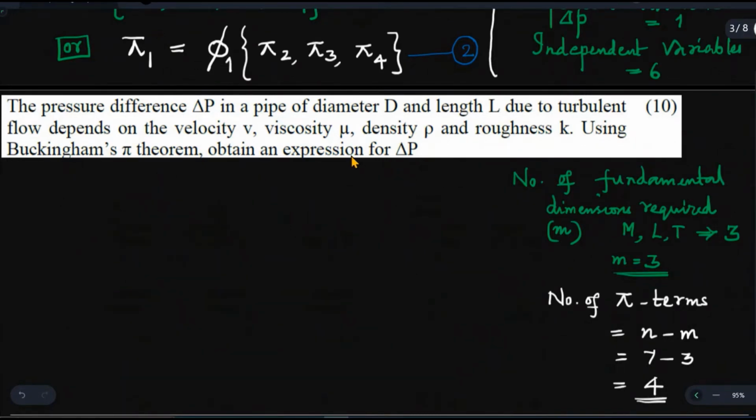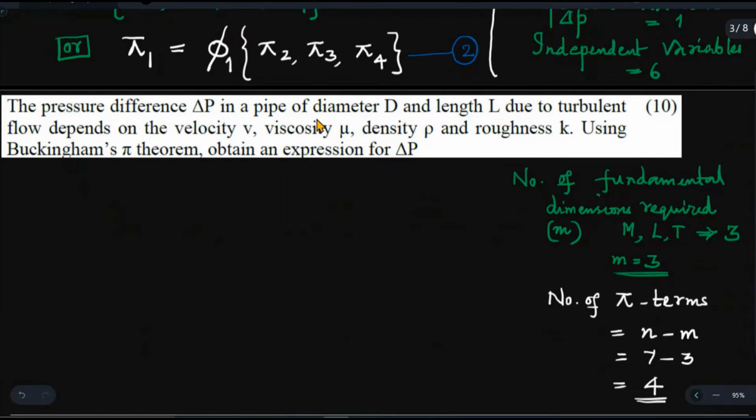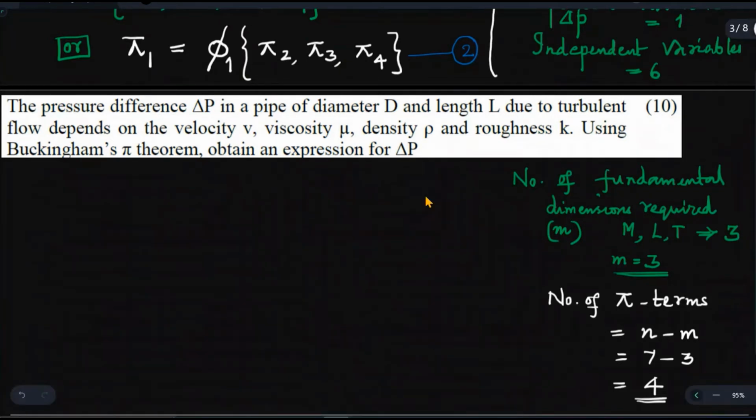See, this is another objective also. Once you get the pressure drop in the pipeline through which the turbulent flow is proceeding, you can even find out the head loss due to friction. So basically, you're finding the head loss due to friction, pressure head drop due to friction. And in that way, you may be in a position to arrive at the Darcy-Weisbach equation. So sometimes in a question like this, you will be asked to obtain ultimately that important equation, Darcy-Weisbach equation, for finding the loss of head due to friction through pipelines in a generalized flow situation. Especially here it is for the turbulent flow.